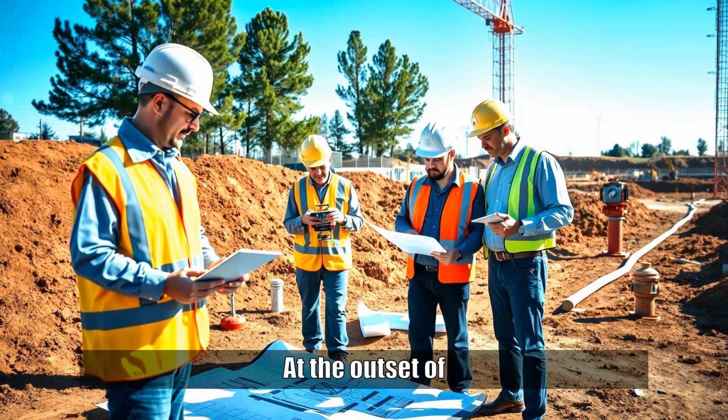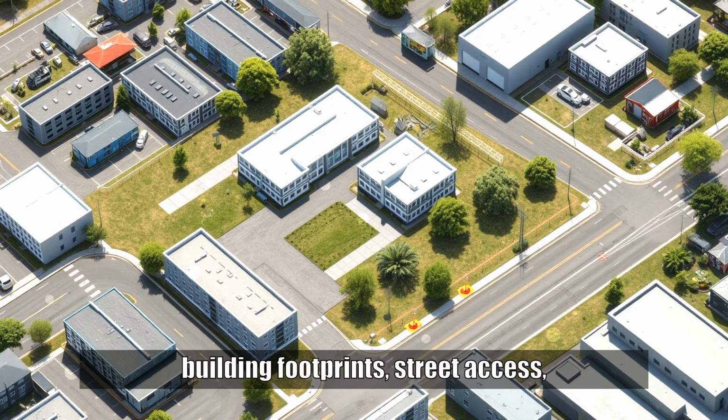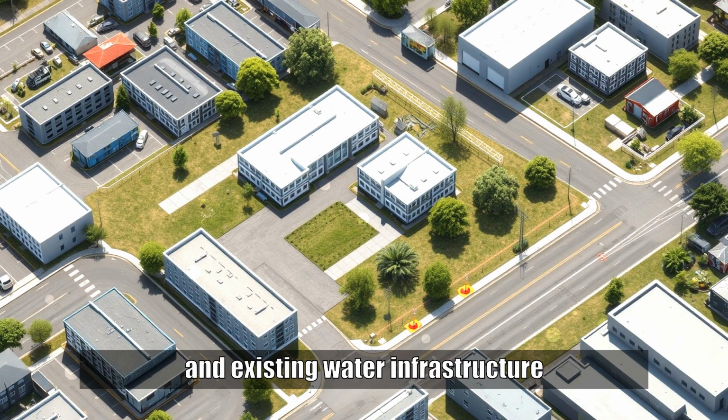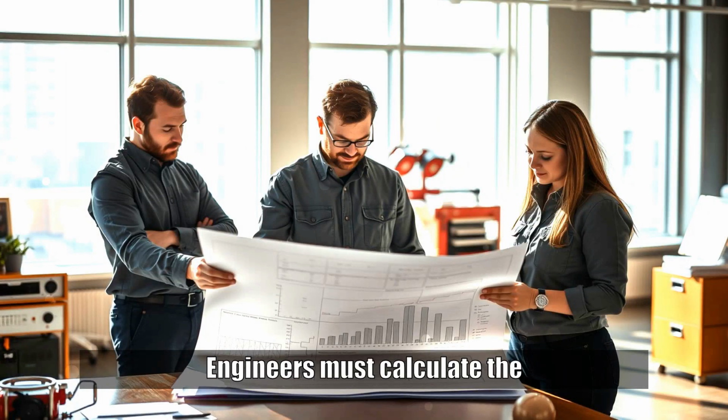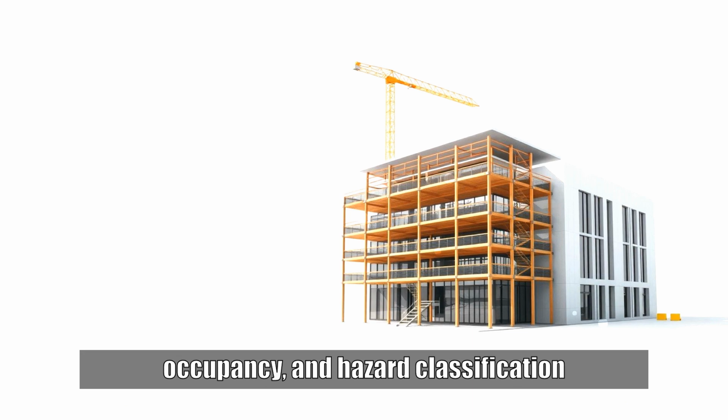At the outset of any hydrant system installation project, the first step is site assessment and design planning. This includes evaluating the layout of the premises, building footprints, street access, and existing water infrastructure. Engineers must calculate the required fire flow, the volume of water needed per minute to effectively combat a fire at a given property. This depends on the building's size, construction type, occupancy, and hazard classification.